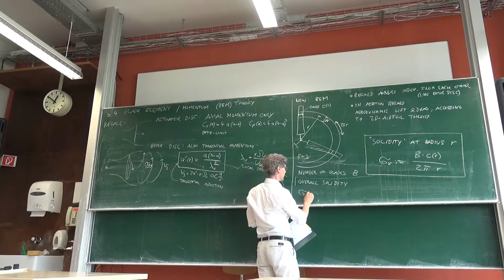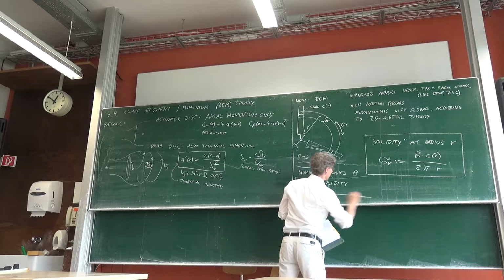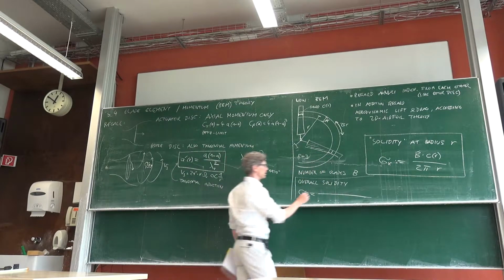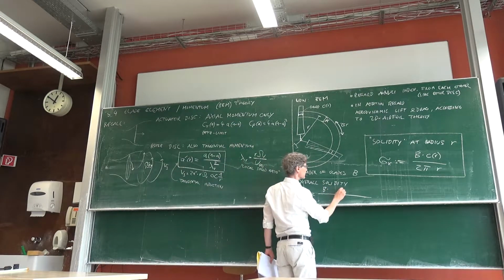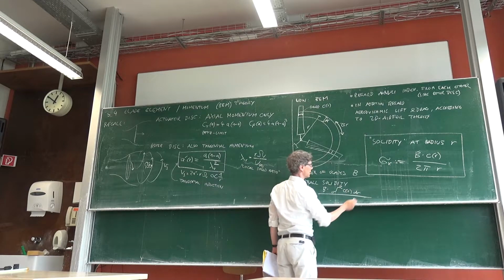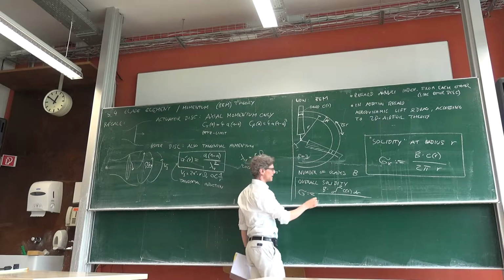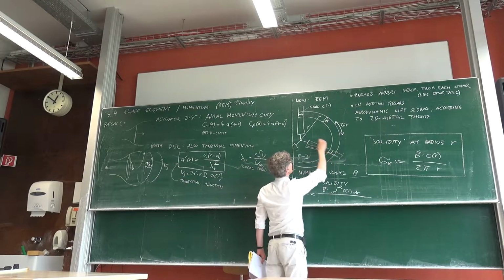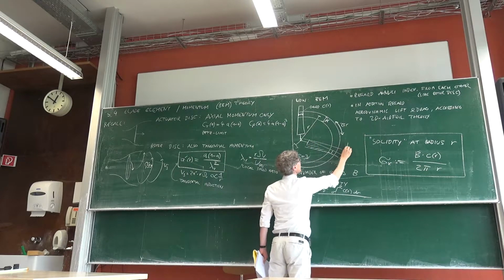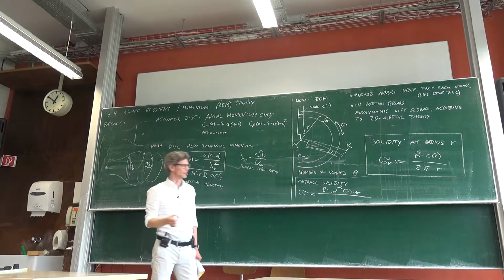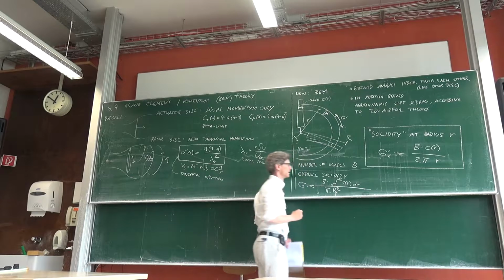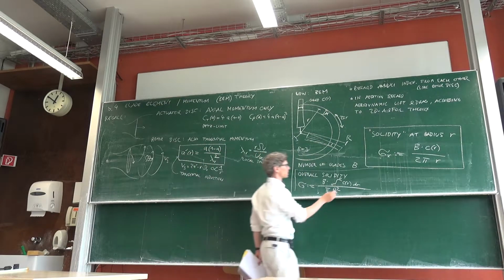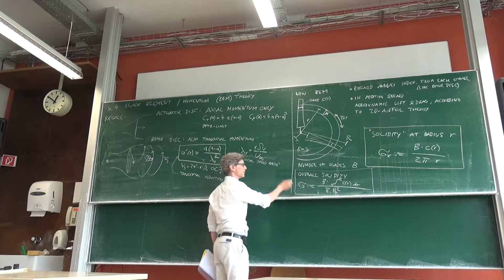So sigma, what is it? It is the integral of all the chords, so it's B, assuming all blades are equal, right? So that's what we will always assume here. So B times the integral from 0 to big R of the chord times dr, that's the total area of the blades, right? Divided by the total area of the disk. I should also define the total radius is big R as before. So we divide this by pi big R squared. So this would be the overall solidity of our actuation disk, our wind turbine.